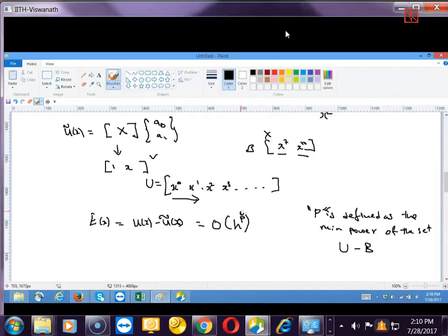That is only guaranteed if the choice of the polynomial you make in the trial function has all the lowest powers in it. Okay, so with that, I would say this completes your h convergence requirements. The other type of convergence is the p convergence.